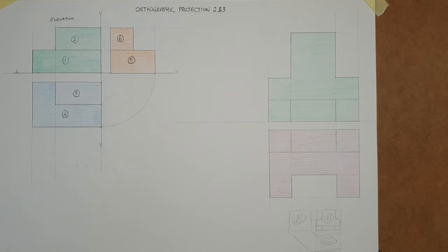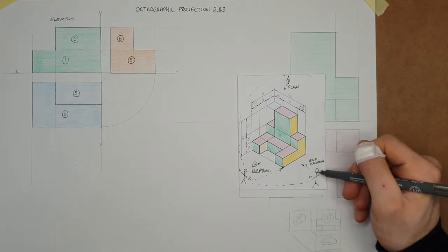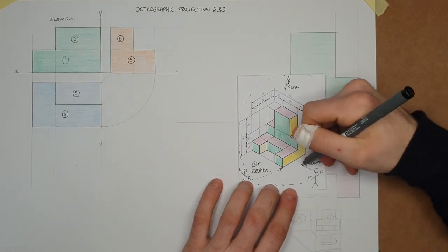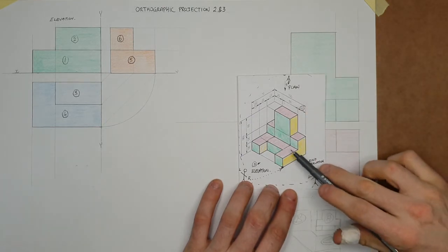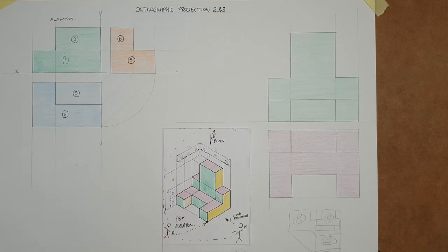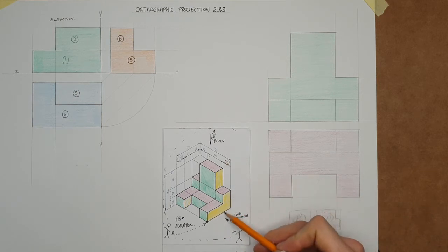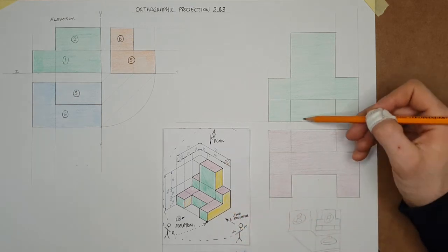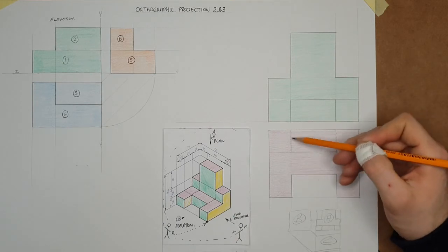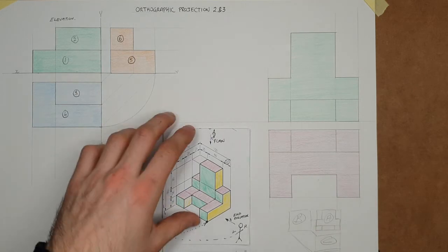The final step of this drawing is going to be the end elevation. So once again, as I said at the start, if you look in from the right hand side of an object, you project your view on to the left. This time we can see the yellow surfaces, these two. We can see the heights of the object, and we can see the depths of the object. So the heights coming from elevation, and all of the depths, these 25, 25 and 25 coming from the plan. So heights from elevation, depths from the plan.